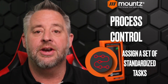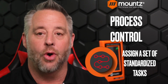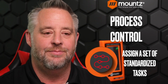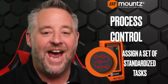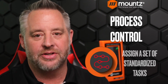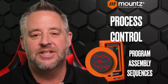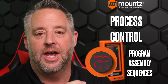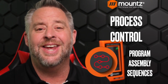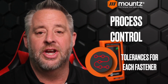Our number four item is going to be process control. And basically, this is just a set of standard tasks within the process. But what is nice about having process control around the fastening process is that we are able to program assembly sequences that are done for a specific fastener within that particular step. So that gives us the ability to have tolerance done for each fastener.